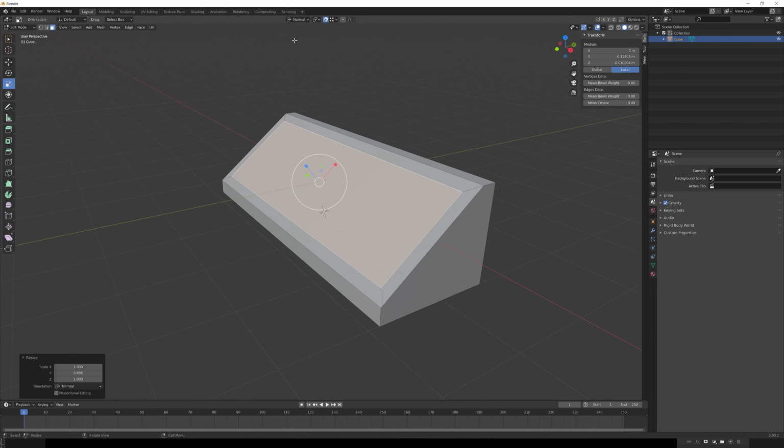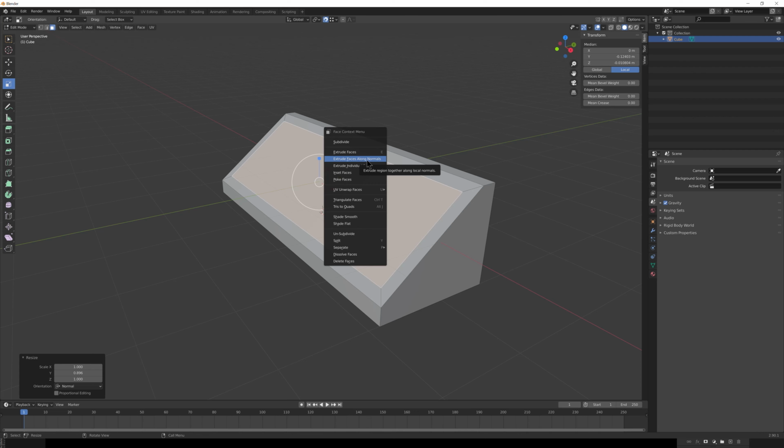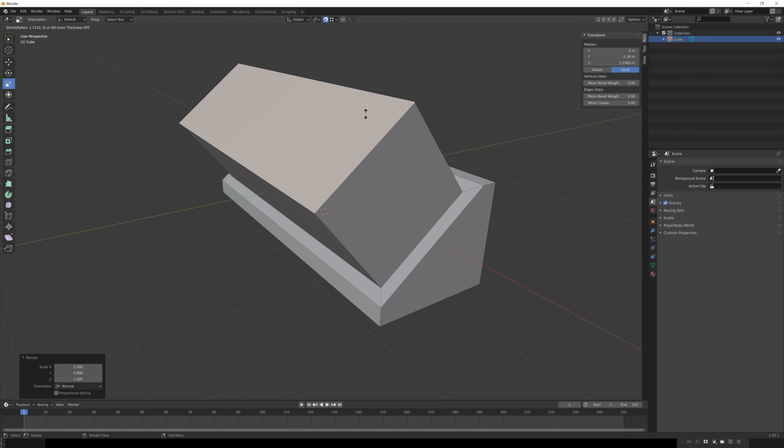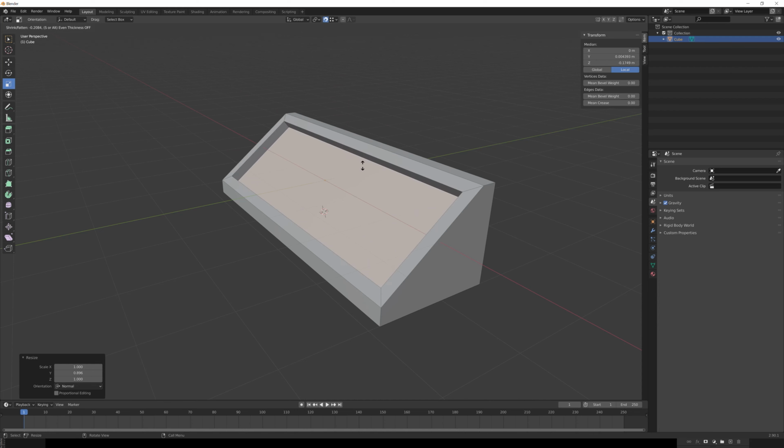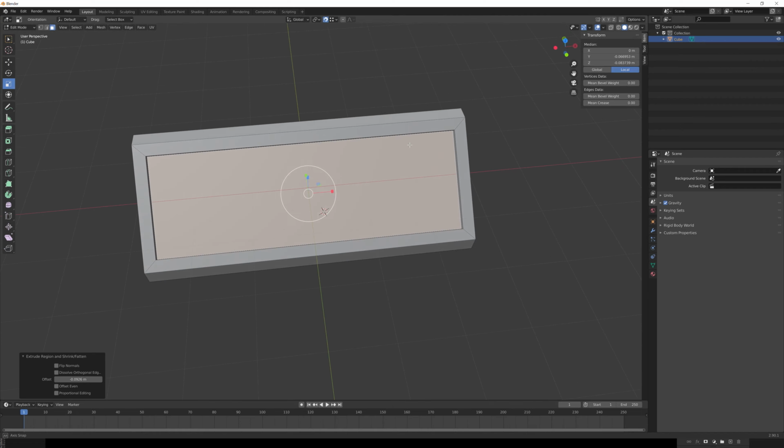Now that I have that set up, we can of course change that back to global if we want to, and I'm going to extrude it inwards so that there's a central area where everything's located. I'm going to go to Extrude Faces Along Normals. Once again, I hit the right-click button to access this menu of different options. Now once I've done that, you'll see that it's moving along the surface normal. And since I've kept everything pretty well defined, it's going straight out of that surface and into that surface. I'm going to push it in just a little bit to give it some kind of depth.